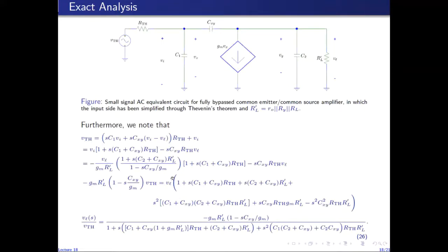Take the LCM, take the denominator onto the other side, take VL out common, simplify, and then take the ratio of VL to VThevenin, which will be equal to this factor divided by this factor in the denominator. So this factor, VL over VThevenin, will be equal to this factor divided by this factor in the parentheses. This factor in the parentheses can be obtained by analyzing this expression.